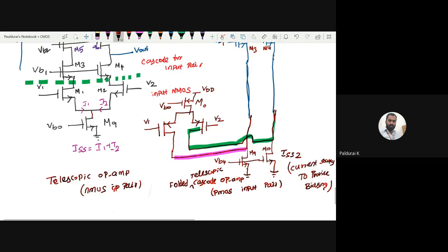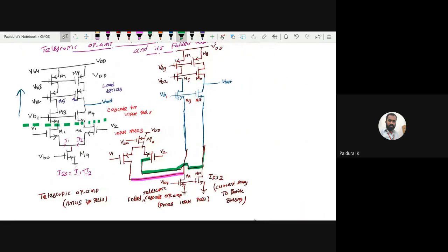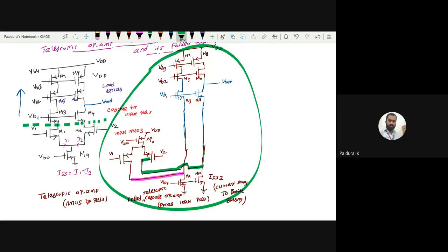So this is my fully simplified circuit. This is it. How many transistors actually? This time 11 transistors. But how many are we stacking at the output side? Only 4. Last time, including the tail current source, there would have been 5.